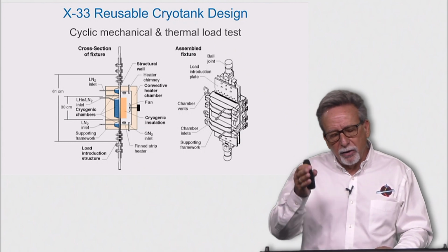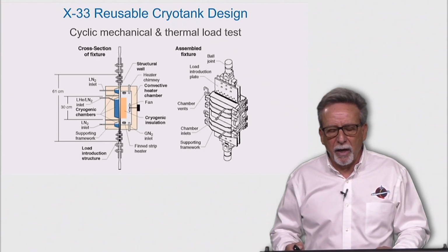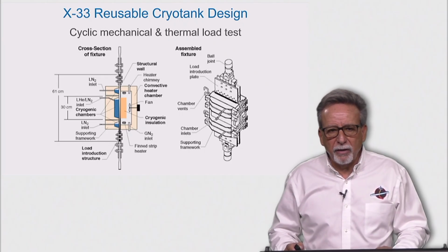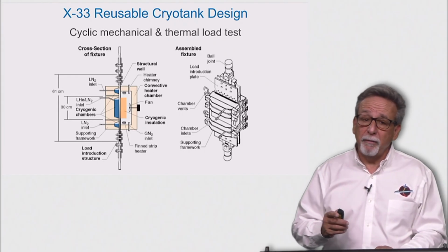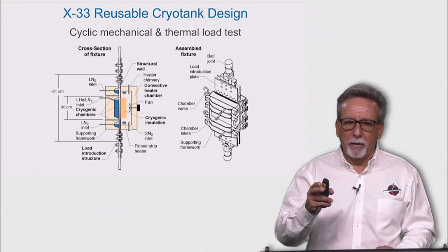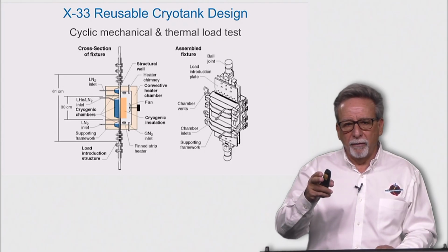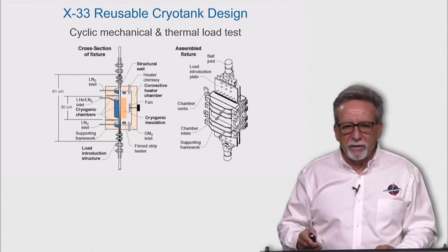The contractor had conducted numerous tests in a facility very similar to this, in plane, directly in line, as shown above, and their specimens survived multiple loads, many times the expected life cycle for the reusable cryo tank. One small but very important detail was omitted in this test: the simulation of the pressure pillowing of the cryo tank. There was no curvature as the loading occurred.